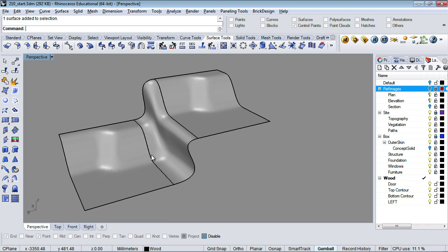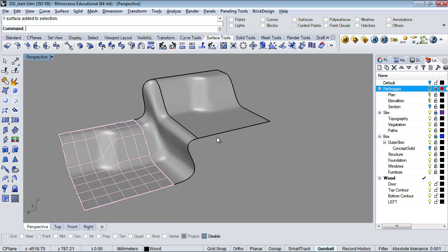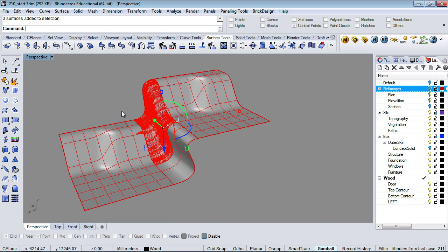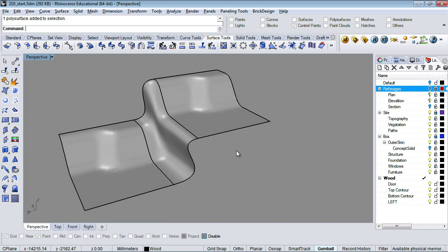And if we want, we can select all of those surfaces and join those into one polysurface, so it's all selected at once. Okay? So that would be my technique. That's what I want you guys to work on. Work on the C-planes, building out those profiles, sweeping into sections, and maybe work in smaller pieces, but think about how you would break up this surface so that you could use this blend tool to make it easier to build up that surface in chunks.